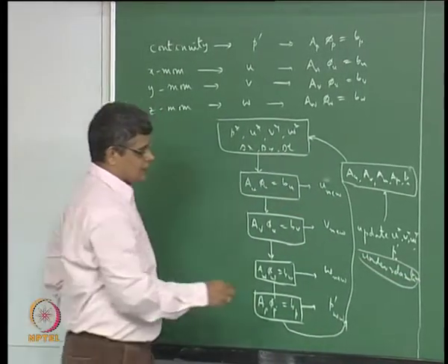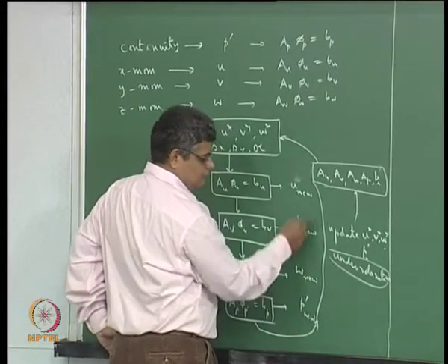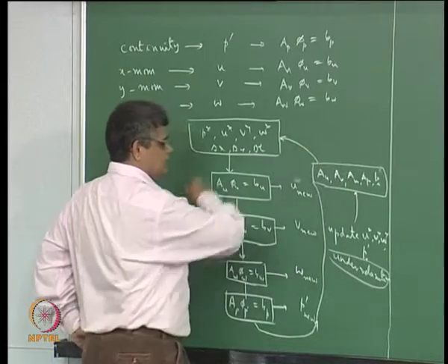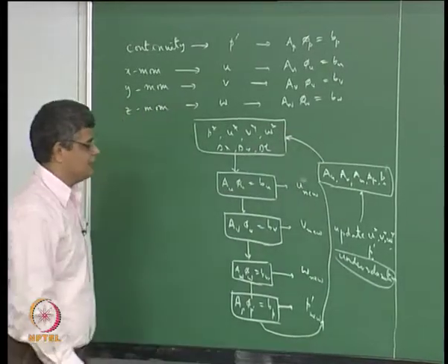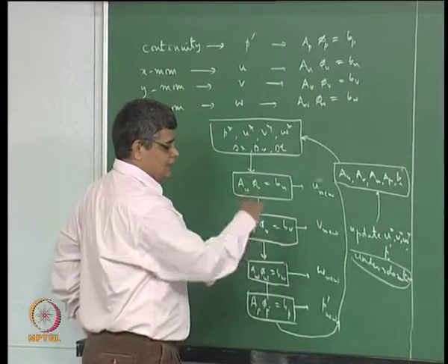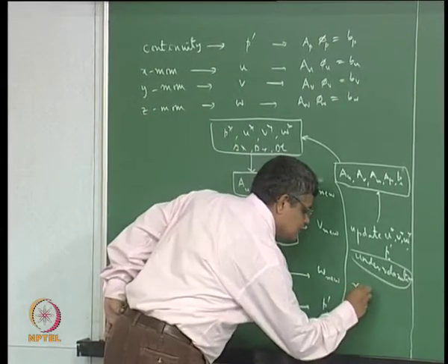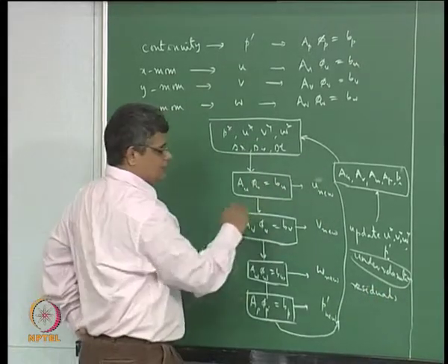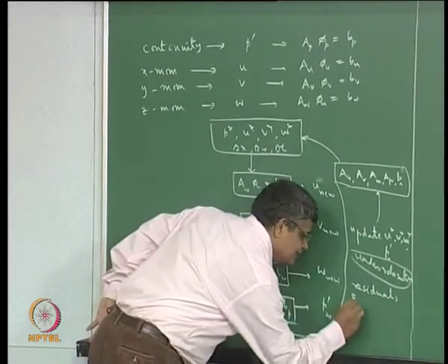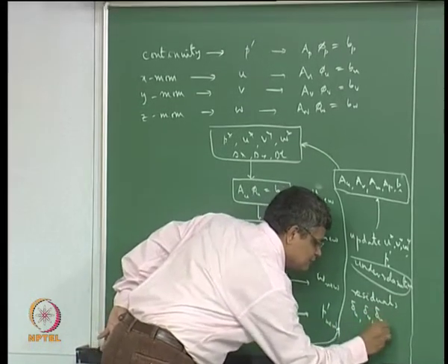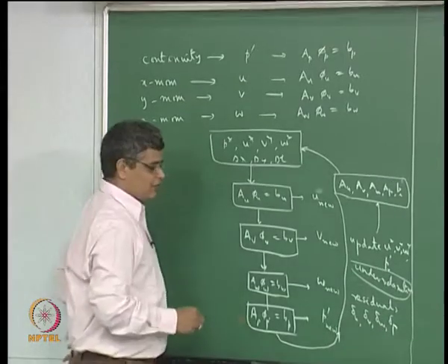Okay, so we under relax in evaluating from the new values the updated values here, and then we go back, we go through this loop several times, and then we monitor, we go until the residuals of each of these equations, so we can call them delta U, delta V, delta W, delta P, become very small.